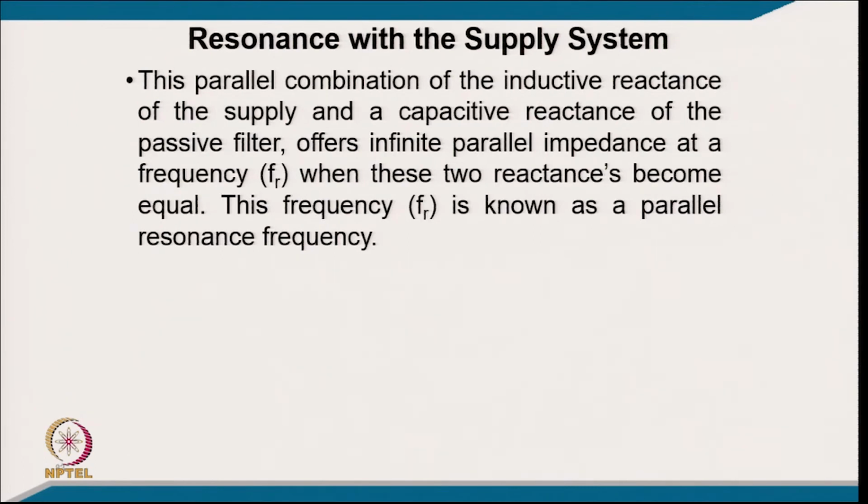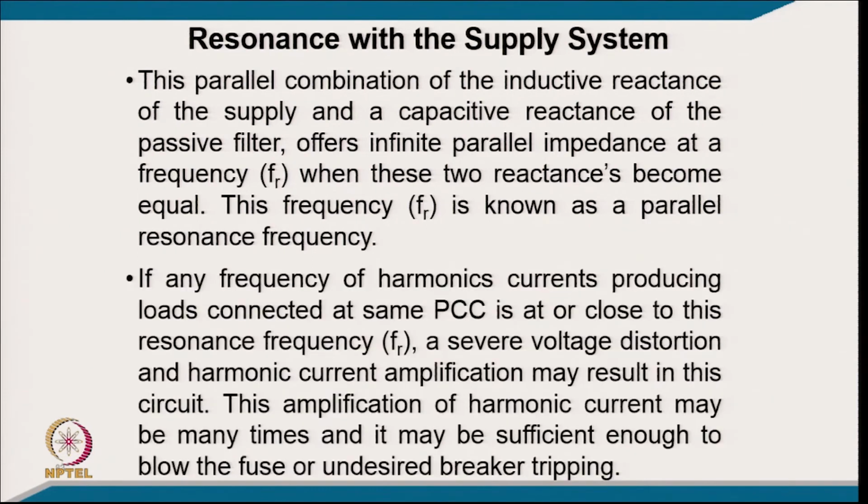This parallel combination of the inductive reactance of the supply system and the capacitive reactance of the passive filter offers an infinite parallel impedance at a frequency FR when these two reactances become equal, and this frequency FR is known as the parallel resonance frequency.